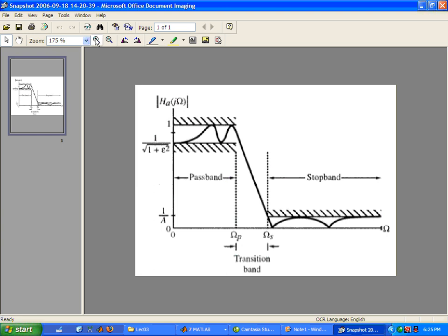build your filter. So the basic building block is the filter order. So the greater the order of the filter, physically, the more of it there is to build. So that's like more resistors, more capacitors, more whatever it is. There's more parts to the filter in designing it.